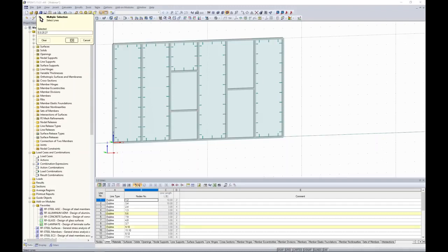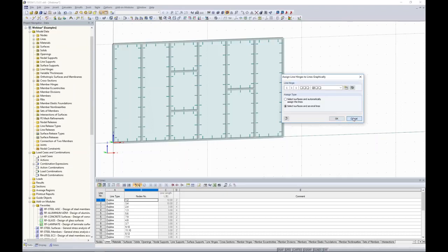So you can see the benefit here of utilizing that Move Copy tool so that we don't need to individually apply these line hinges to each surface like we're doing now for these smaller segments. So we'll go ahead and do the same thing for the 5th panel point location, and finally for our smaller panel here, we are done.